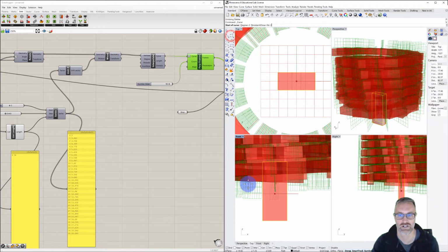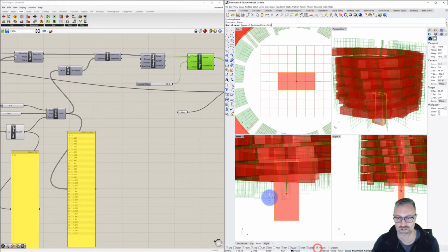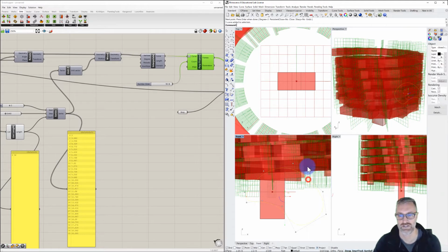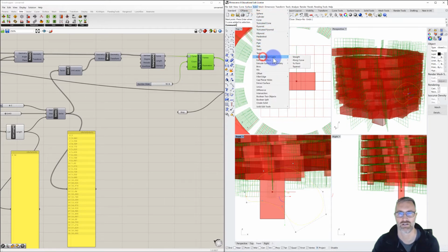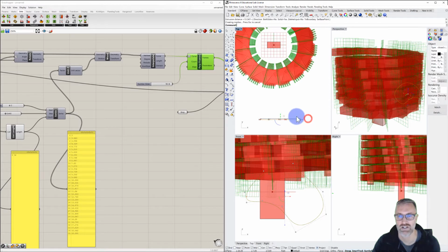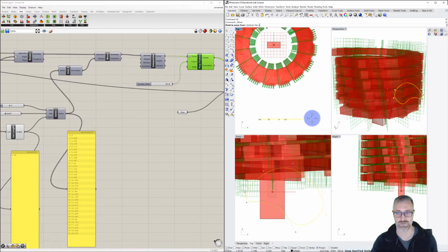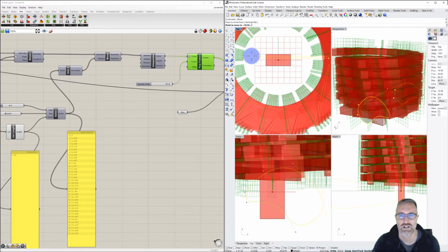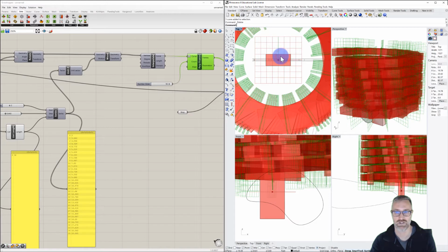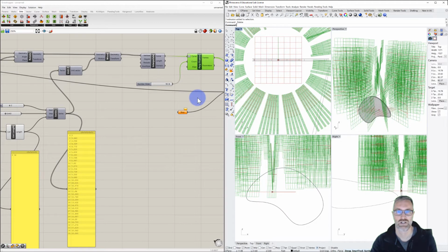And maybe what I'll do is I'll just draw a more complex shape. More of a kind of scale. Oh, I do want to close it. But I also want this to be asymmetrical. And then let's extrude it a little bit. We'll do this as a solid. Extrude planar curve straight. Doesn't have to be too thick. We'll take both of these, we'll move it over. And we'll make sure that it's centered over the point. And now let's set this to be the B rep.